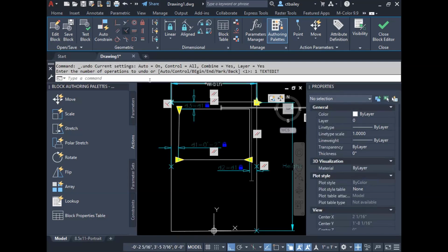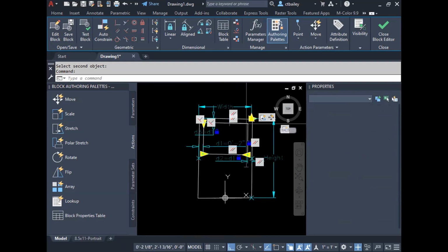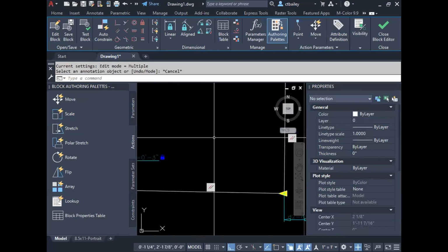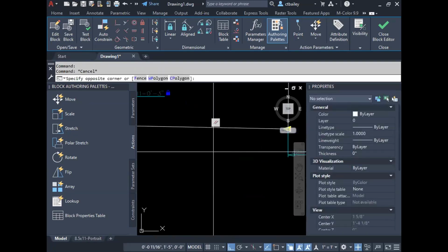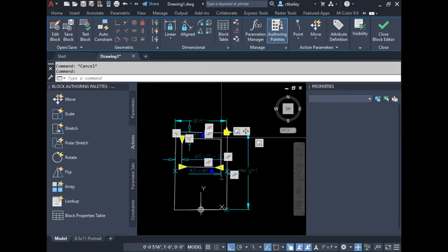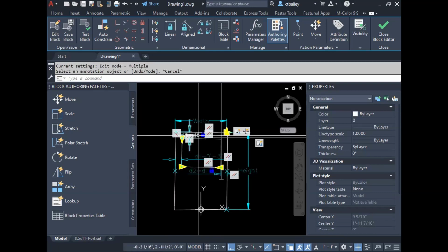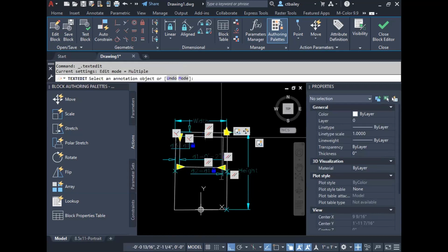Let's go ahead and throw a perpendicular in there. 1, 2. Now change D1 to 3 inches. There, that worked. Okay, so you've got to sneak up on it. I mean, I see it in the thing. How did you? Oh, it's over on there. Well, take a look at D2. D2 is equal to D1. And D3 is equal to D1 also. And so the only number that I have to change here is D1. So let's go back to 2 inches there.